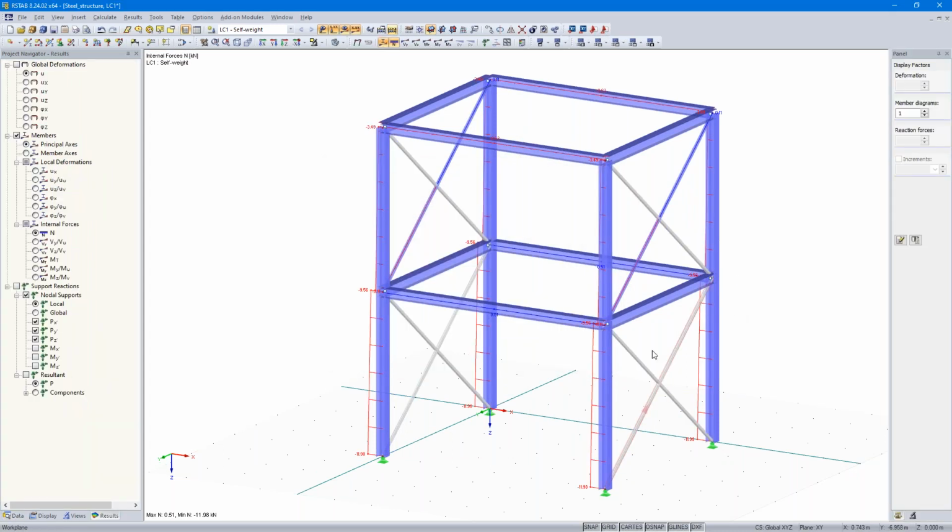Now these tension members have failed, and this one is still there, and this one, and that's why the calculation is okay for this load case. If you have a load combination, for example with self-weight and wind in Y direction, the members here are reactivated. We don't lose them for the whole time.